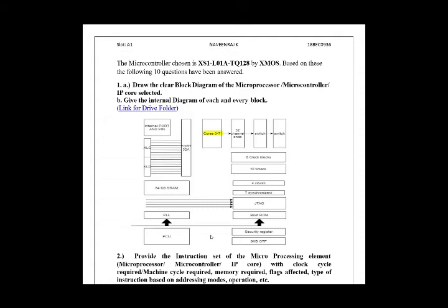Talking about the boot ROM, it runs a simple operation. We go step by step. Suppose there's a primary port, and in that boot we'll be setting each bit of the security register. We'll talk about the security register in a few moments. Suppose bit 5 is not set, then we again boot according to the source pins. So we'll assume bit 5 is set, which means bit 5 equals 1.